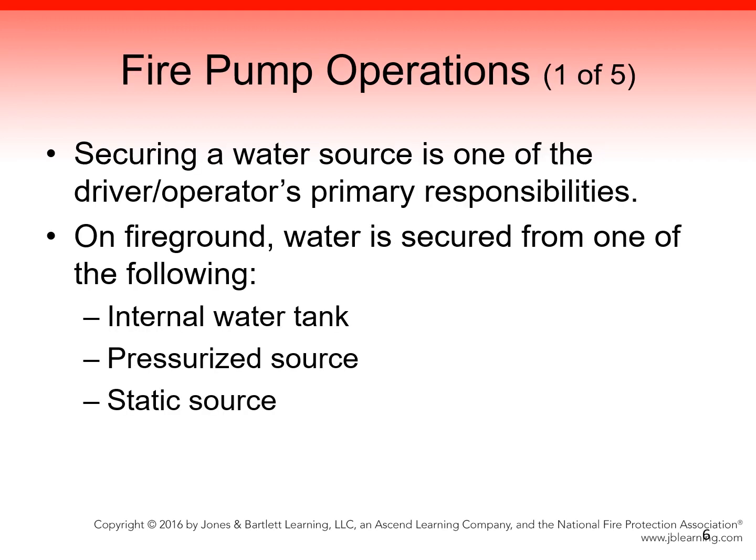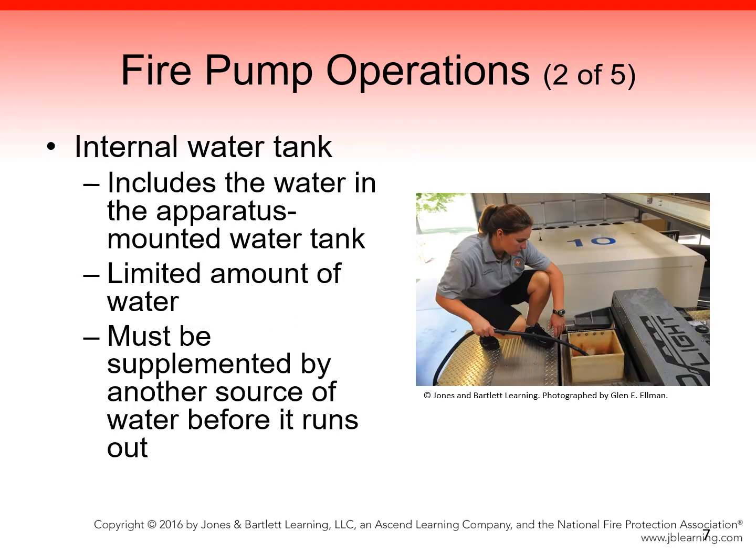Fire pump operations. As the driver-operator, securing a water source upon arrival on scene is one of your primary responsibilities. While on the fire ground, you will operate the fire pump from one of three different water sources. Internal water tank includes the water in the apparatus-mounted water tank. It has a limited amount of water and must be supplemented by another source of water before it runs out.